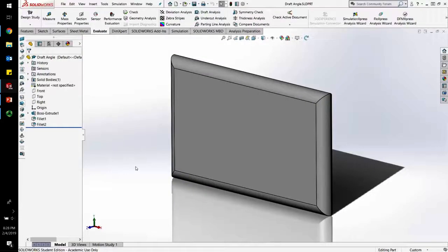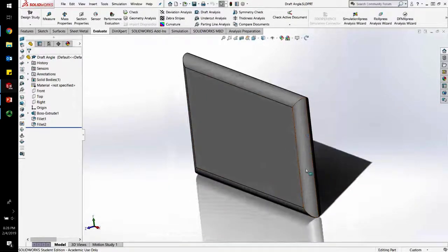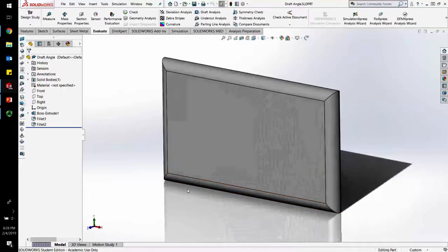As shown here in SolidWorks is a basic extrusion of a rectangle, which has added fillets to each edge. In order to be able to check the manufacturability by injection molding, the fillets and radii of a part should be as generous as possible. The desirable minimum under any part, however, is 0.5 millimeters or about 0.020 inches, being that a 1 millimeter fillet is the most preferable. To determine if the fillets and radii of the part is able to be injection molded, there is a built-in tool in SolidWorks to help check.